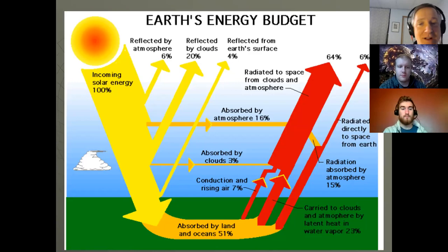Usually, we have water molecules in the atmosphere and we have clouds and things that kind of cut back that loss. And then, we talked about the condensing of water at what's called the wet bulb temperature. And once you start condensing water, you basically put the brakes on the night temperature, because if you remember that phase diagram, you start the latent energy changes, but the sensible energy doesn't once you start condensing water.